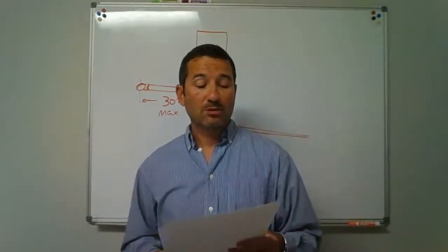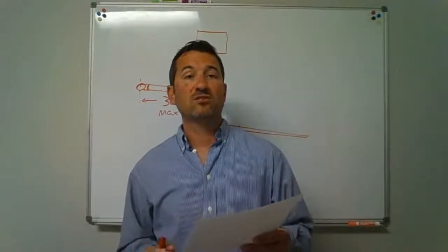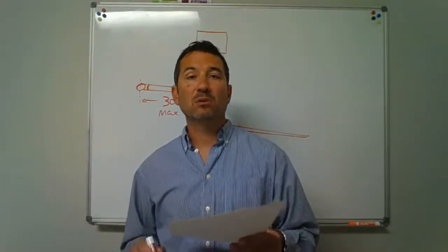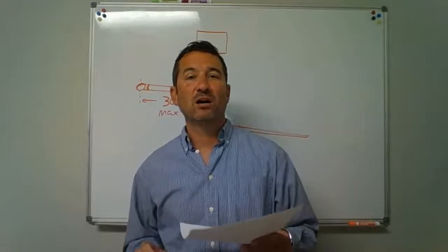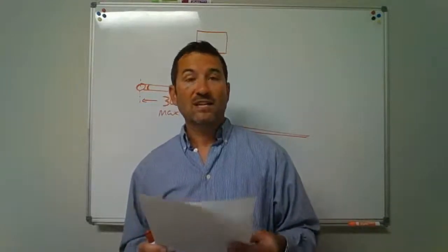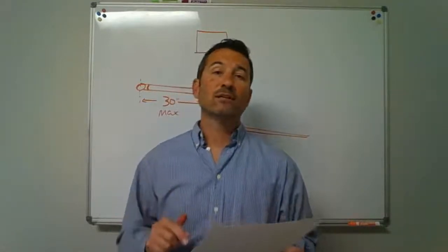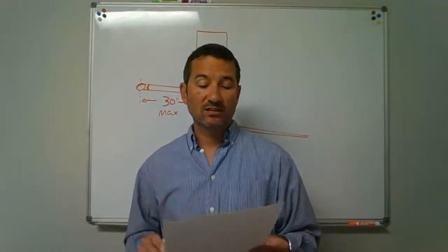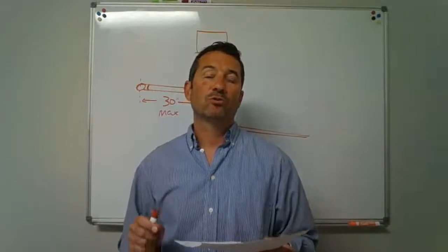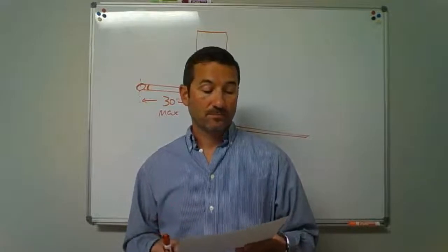The standpipe shall extend a minimum of 34 inches above the base of the clothes washer. Question 9. Drinking fountains can be connected both directly and indirectly to the drainage system. Is that true or false?